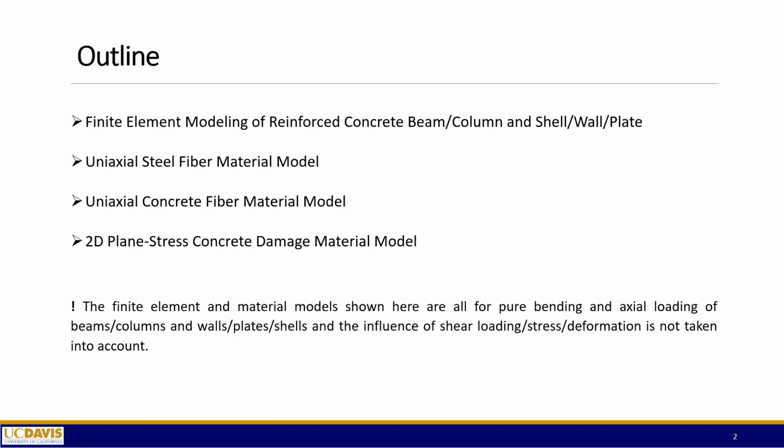I should mention that the finite element and material models shown here are mainly for pure bending and axial loading of a beam column or walls, plates, and shells, and that the influence of shear loading or shear deformation is not taken into account. Other researchers have developed additional methods to mitigate the effect of shear deformation, but that is not considered here.